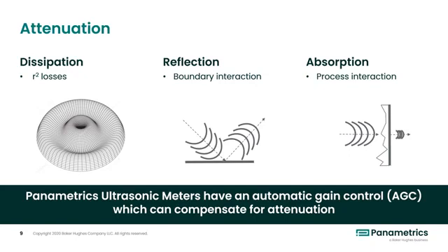Reflection occurs when a sound wave bounces off of an object. We can see this in action when we hear an echo as the sound wave bounces off of a wall and comes back to us. In ultrasonic flow measurement, we can actually bounce a signal off of the opposite side of a pipe to be able to get a flow measurement. However, reflection is not always our friend. Second phase materials, such as a solid catalyst in a flare line or gaseous bubbles in an oil pipeline, can cause the signal to bounce away in a different direction than what is expected.